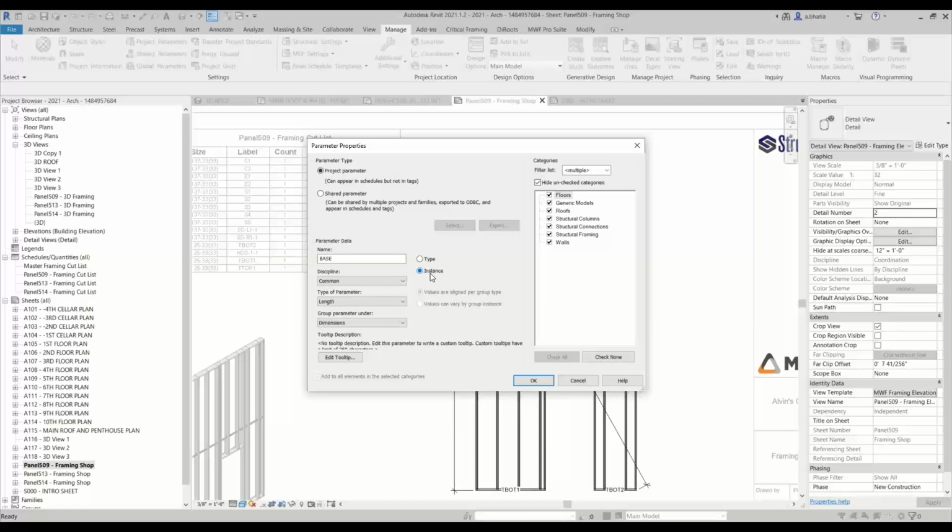I know those are ridiculous colors for a building, but if you have all of these wonderful options, you don't want to create so many types of families and load your project up with so many different types. Instead, a lot of clients like to use the instance parameter for this. So what I would do is call it finish, and make that an instance parameter. Now let's set up a finish parameter, just as an example.